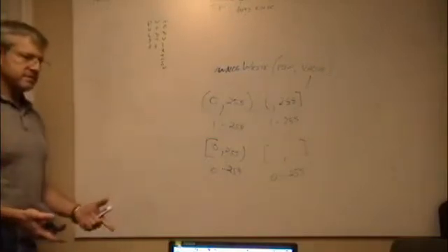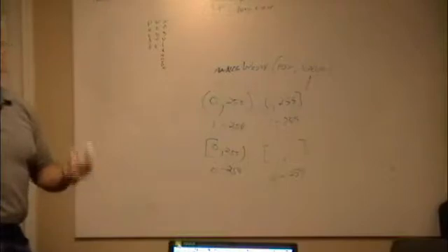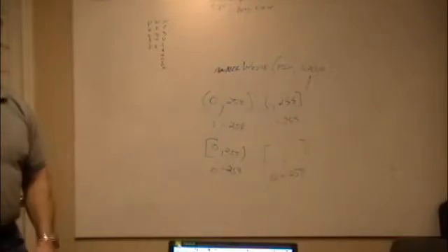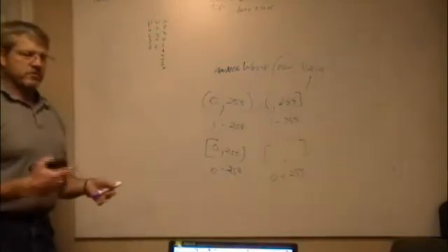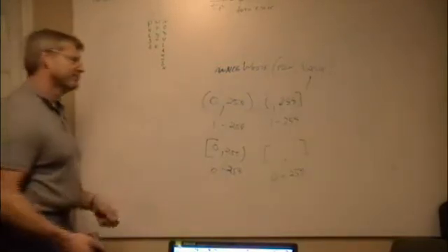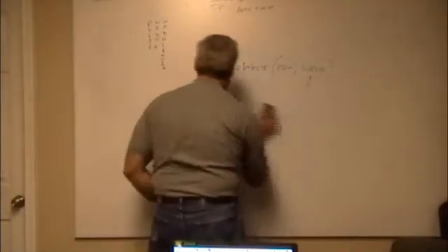The reason for that is that timer 0 and timer 2 are 8-bit timers. Timer 1's a 16-bit timer. So it limits... timer 0 and timer 1 can only run a short amount of time before they overflow. So analog write was written absolutely with exactly what we're doing here in mind.